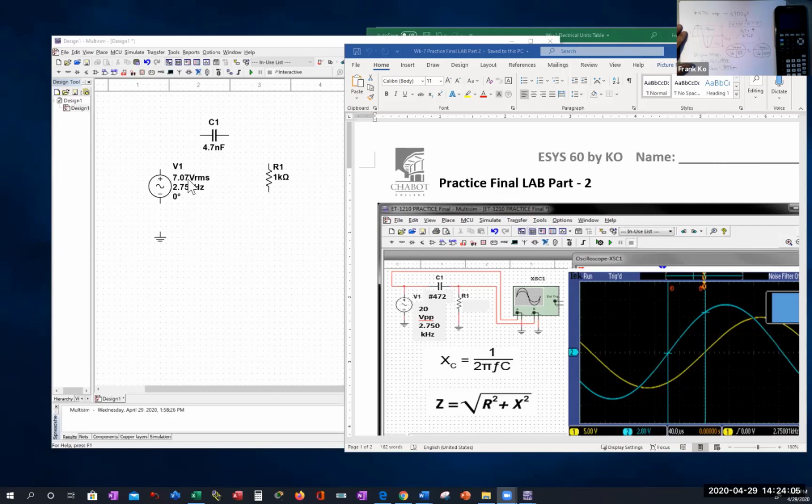The only difference is the format of voltage here is expressed in RMS and the format of the voltage here is expressed in peak to peak. Why is there a difference? Because the code guy wants you to think. He wants you to interpret what a 472 is, and you actually remembered how to convert the code of 472 into a capacitance value, which worked out to be 4.7 nanofarads. The code guy wants you to think.